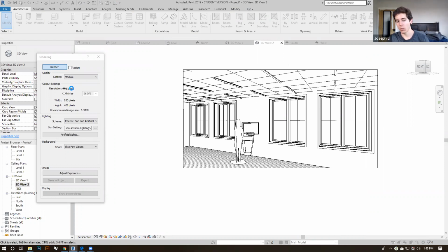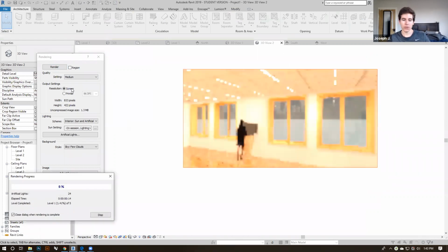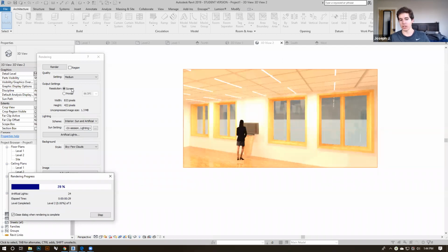Just to kind of recap while we're waiting for that to finish. Really, all the useful commands you need to know in Revit are MV is move, AL is align, CO is copy, DR is door, WN is window. Ceiling and floors, I don't think they have a command. You just have to go into top-down view and click on the door button up here.